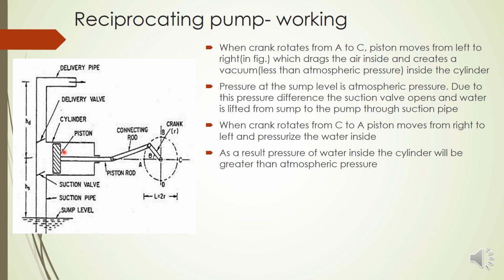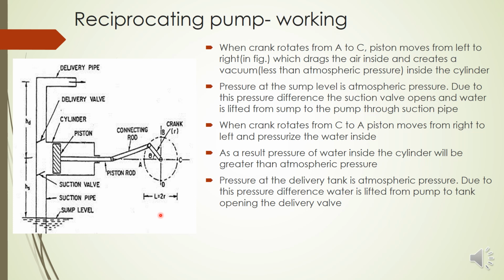more than atmospheric pressure. Now here we have only atmospheric pressure. So again we have created a pressure gradient. So this delivery valve will open and water will get lifted to the tank. So this working is more or less simple.